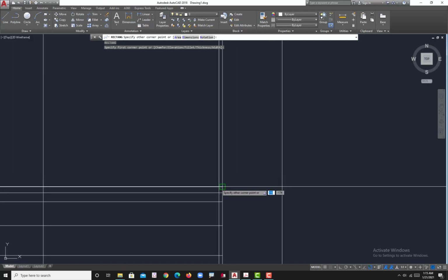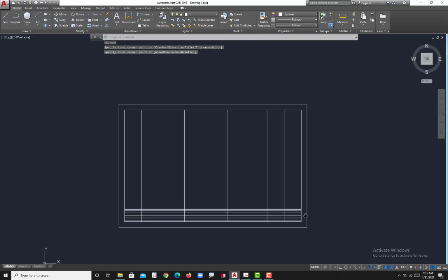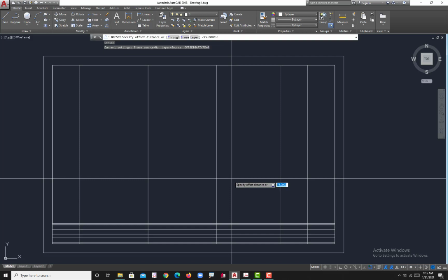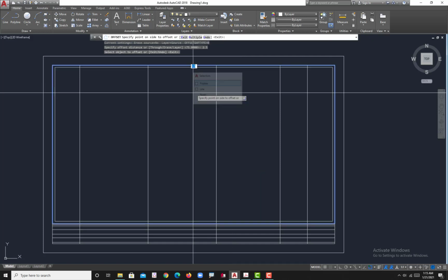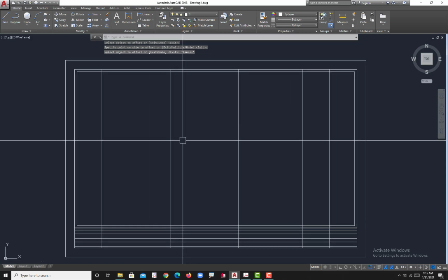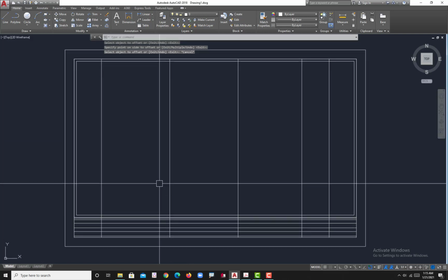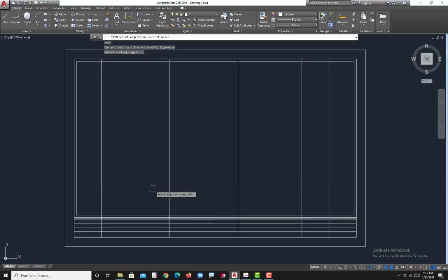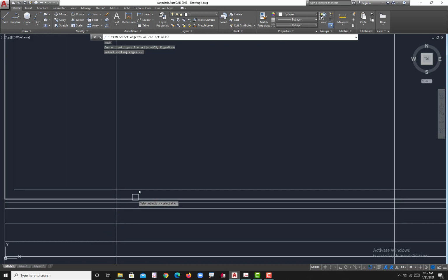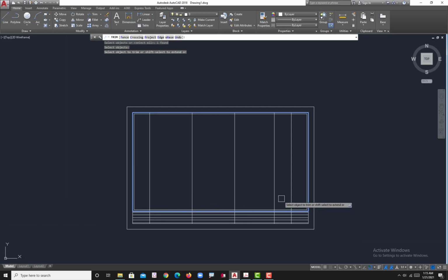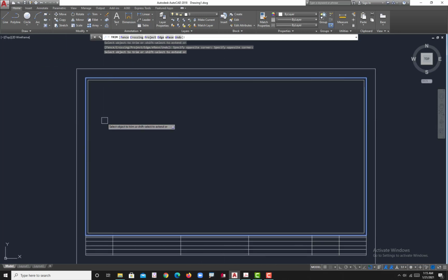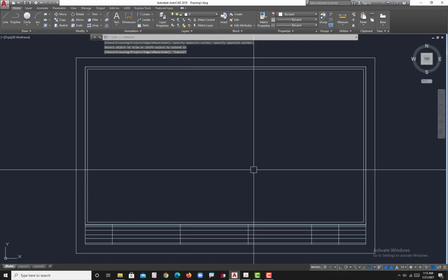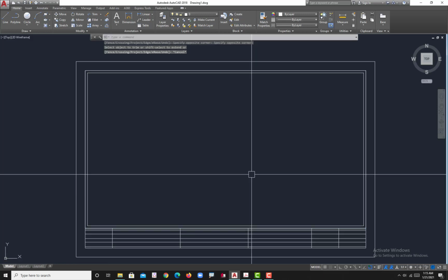Okay, there, and then offset that one to 2.5. Select the polyline. Then I will trim it here, TR, then enter. I will select this boundary, the polyline, and then enter, then remove the unnecessary lines. So that would be my preliminary template.